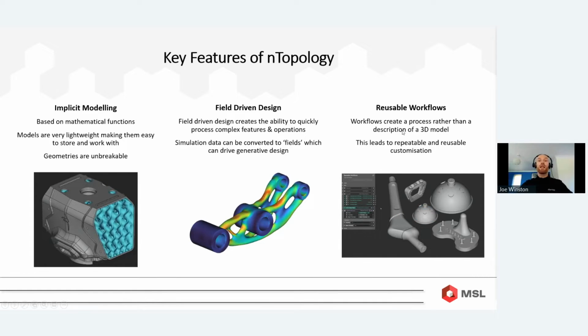In a traditional CAD package, we might update a property, a radius at the top of a design tree, and further down the design tree we would have errors and the model would break. In nTopology, we don't have those issues, and it gives us the ability to create reusable workflows. In the example down here, we can see some patient-specific CAD data, and within nTopology, we can apply a stochastic lattice to each of these models.